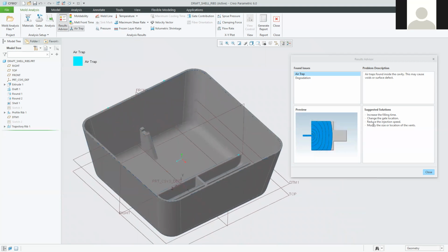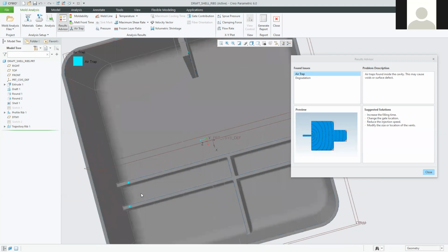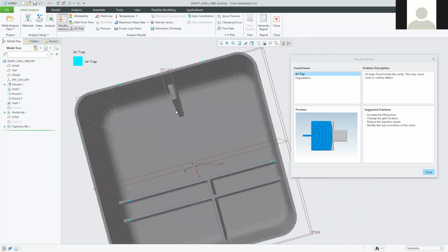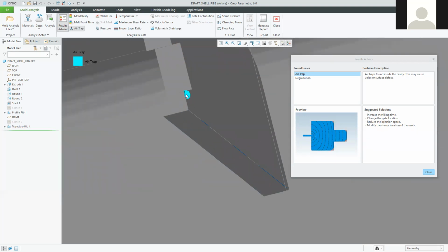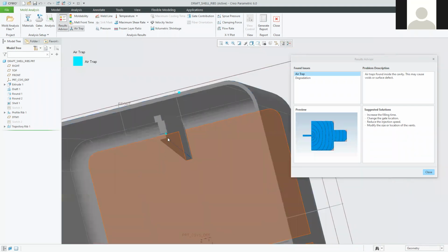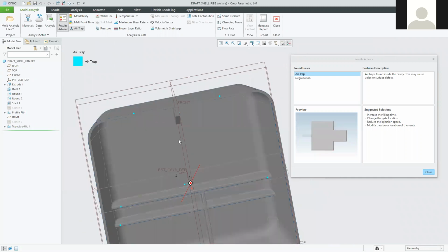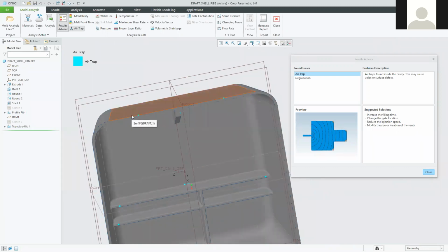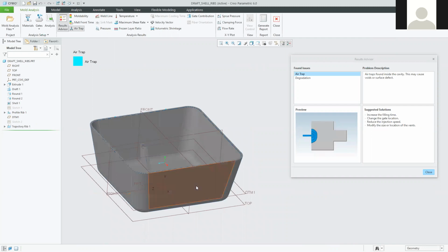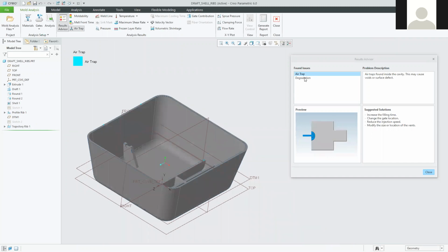Other solutions we've been given there. So is there anywhere else? Yeah, we could do the same thing over here. So we could address it in that way. We could make a change to the actual design itself, and put sacrificial bits of material into the design and sacrifice the speed of manufacture, knowing that we were going to have to put a chopping manufacturing step after the molding manufacturing step. But inevitably, you end up having to do that to a certain degree anyway, even if it's just to chop away the excess material where the injection gate is. So that would be one way to solve that.